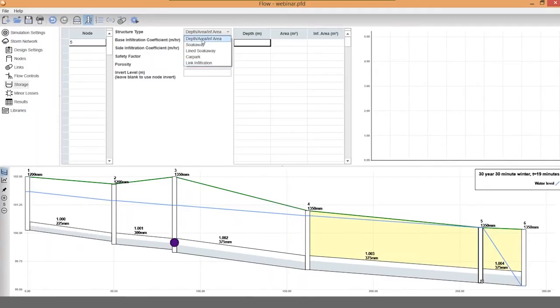In this case, I'm just going to go for a tank, so I can take the depth area case. As I say, because this is just a normal tank, I don't need to specify my infiltration values. However, if your site is suitable for using infiltration, you go out, you can do the site test from BRE365, put the values in, and then the software will analyze the effects of infiltration as well. And it's all based around UK specification.